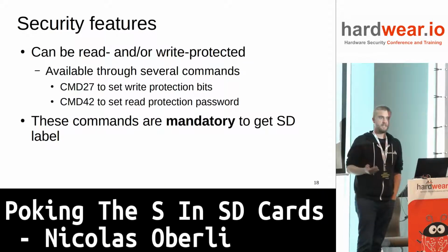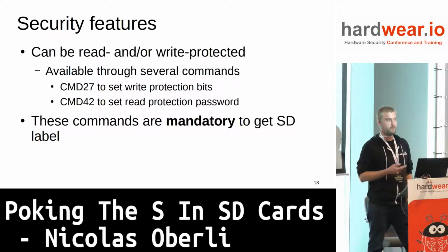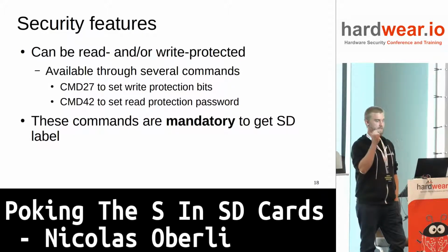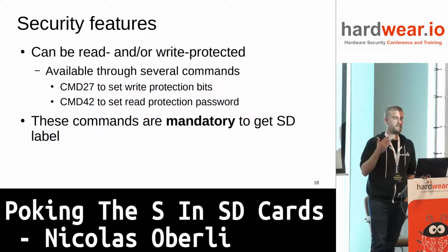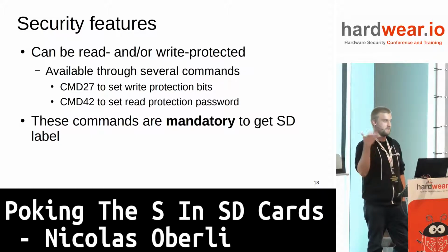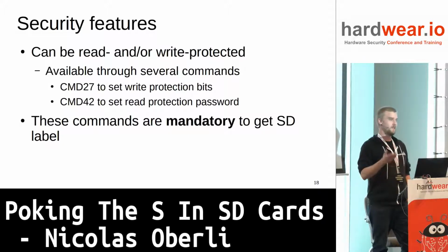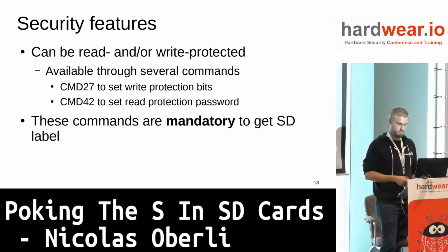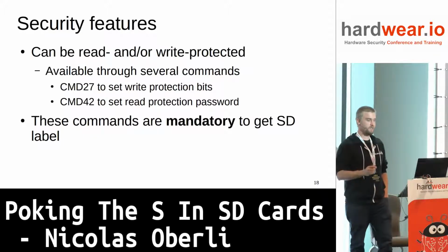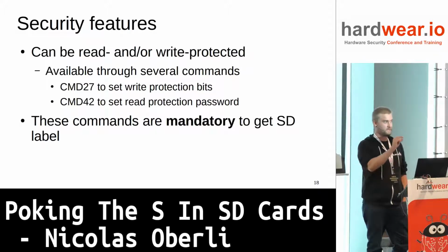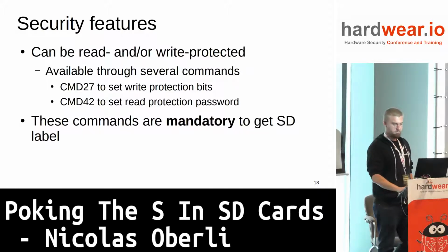So, looking again at the specs, there are two main ways to protect content on the card. The first one is a write protect bit that you can set directly on the card, and another is a command called CMD42 to set a password on the card. Basically, you can put a read password on the card, and you cannot read anything from the card unless you have given the correct password. Fun fact, it's mandatory for all the cards to accept and implement those commands, to get the SD label. So all the cards you can find usually have those commands, even if they are not used.